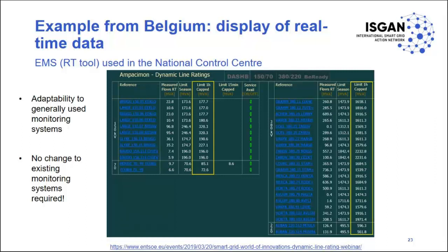So let me explain. When you do dynamic line rating, you have the real-time rating that gives you the load that you can put through your circuit immediately at the same minutes where you are reading the screen. It's the available capacity of the line at this minute. Then with some more computations and algorithms, you can perform some forecasts. So we have forecasts to 30 minutes, 1 hour, 2 hours, 6 hours, or day ahead with 24, 48 hours or more.